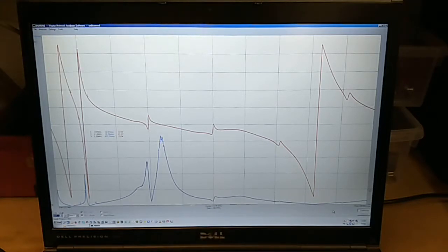There are now, instead of the situation with the vacuum tube generator in part 1 of Transference of Electric Power, when we were just measuring the transmitter, we had the secondary circuit, the resonant secondary circuit. We had the resonant primary circuit formed by the 2 turns of the copper strap, which represents the predominantly inductive part of the primary, in parallel with the high voltage tuning capacitor, and that forms the second resonant circuit.